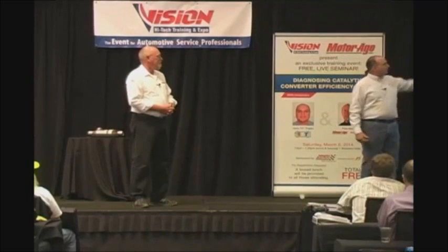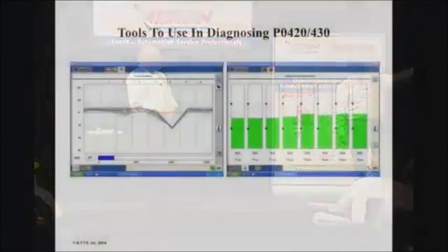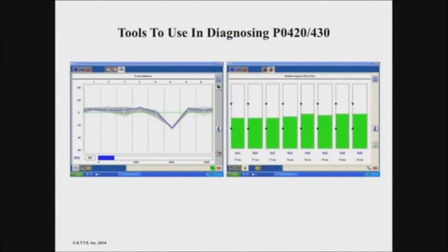Technology just keeps moving. You can do a power balance test right away, just like we did on the old ignition scopes. What cylinder's dropping out? We can do relative fuel injection flow to see if an injector's down, or you can take your regular fuel tester and do it manually per cylinder and see the drop off. Do we have an injector problem? These are tests you got to run.